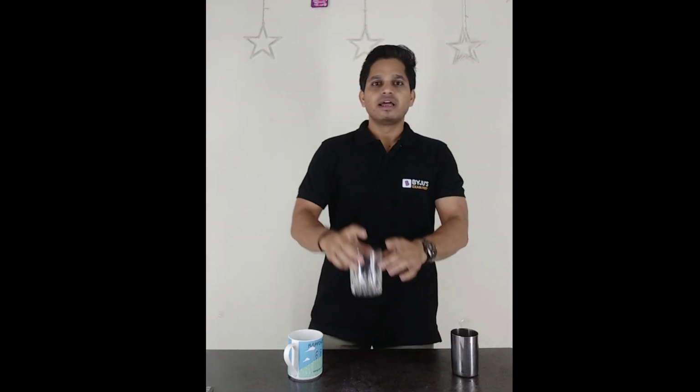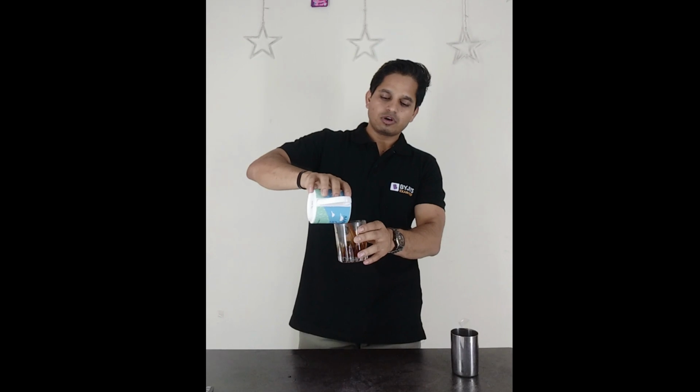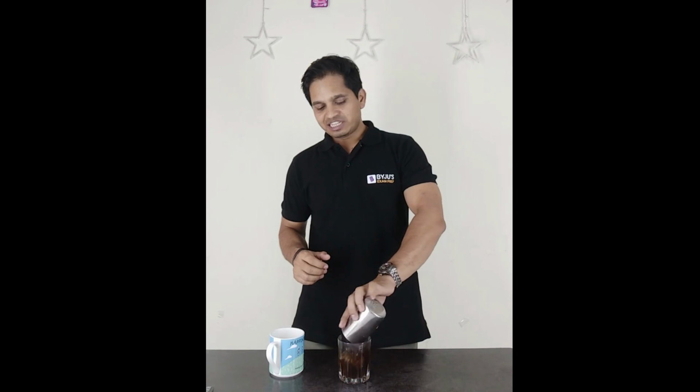So if you are able to understand this, let me explain it one more time. Then we will go to our lecture and we will see how it is happening. So again, coffee is in this cup. It is very hot. It's summer outside. I want to drink my coffee faster. What will I do? Increase the thermal conductivity. I will transfer it into steel cup. Its thermal conductivity is 15 times higher than this glass cup. So heat transfer due to conduction from this wall will be much faster. It will cool down faster. I can drink it faster. But let's say it's winter.